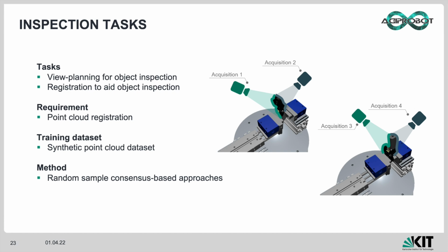For object inspection tasks, the formalized problem of completing product surveys and coverage using a robot-based optical system can be expressed as a view planning problem. To solve this problem, model-based approaches determine robot poses for sensor sensing by pre-planning based on a prior model, while non-model-based approaches determine the next best robot pose for acquisition at runtime through maximizing certain criteria.